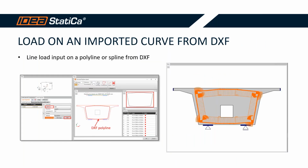And another new feature is that now you can load a concrete detail, a concrete wall on an imported curve from DXF reference. You can import a line load onto a polyline, which can be either a polyline or a spline from DXF, and you can apply it onto your concrete wall. This can come handy, for example, for diaphragms. If you want to apply a line load as seen in the pictures, it can be like a shear flow from traffic load.